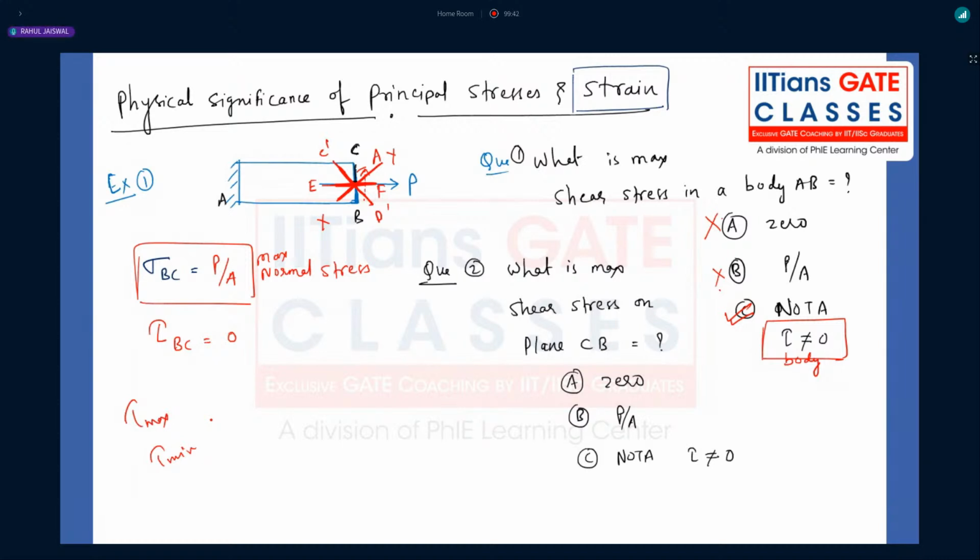Tell me, guys. Because of what? Maximum shear stress, right? Because of the maximum shear stress. And if I take any brittle material, you know that brittle materials are very weak in tension. A little bit of tension you apply, it will fail. Just like window glass, if you just apply the load, it will fail.